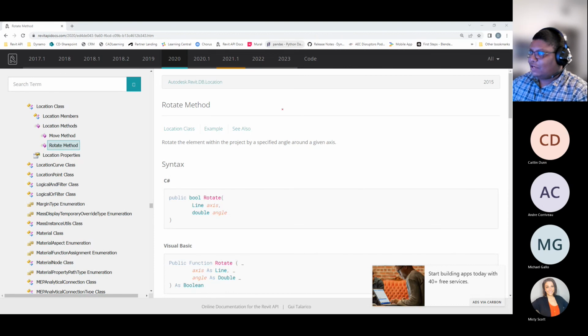In the Revit API, you can go in and get the geometry and get the point for this corner. From this corner point, I can do a transform so that I get another point, 2 feet north of it. Now I have my line, and then I just make an angle and I can rotate it around that point. It's just asking for a line anywhere. But I'm going to see how I did it in my previous work.